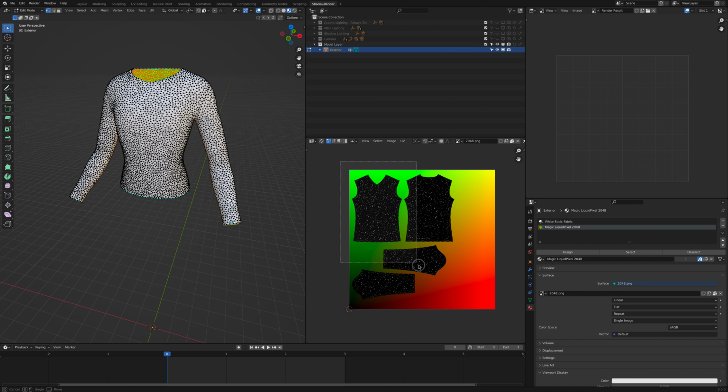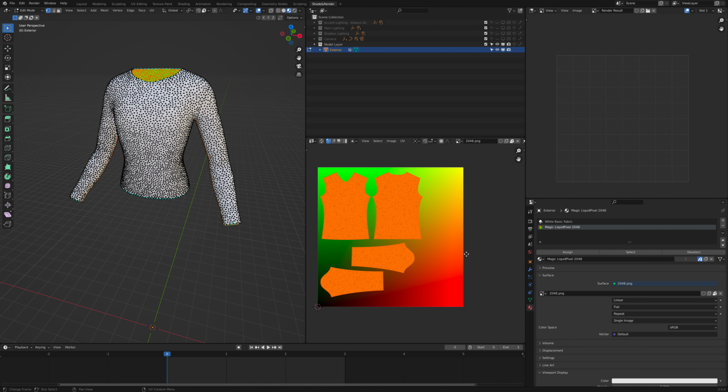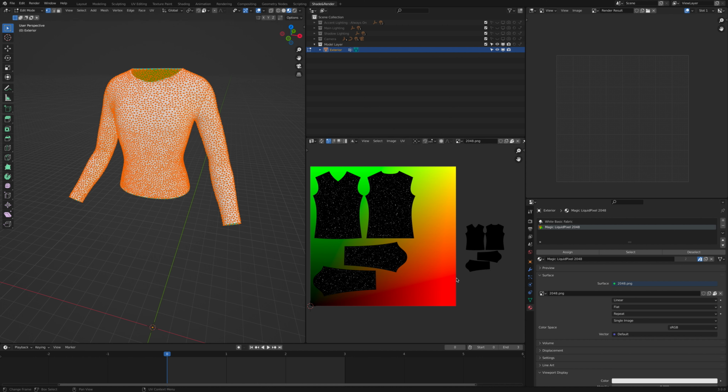But in my UV window, I'm going to go ahead and select all of that. You can either drag around that, or you can also hit A, and it will select everything. And then I'm going to scale and move that off just a little bit. You can do that with S to scale and G to move things, just like in the regular Blender window. So I'm going to make this a lot smaller, and I'm going to move this whole piece right off of our texture.